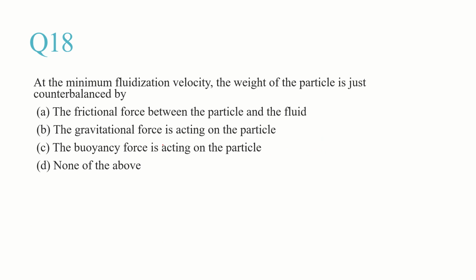This is a similar question. At minimum fluidization velocity, the weight of the particle is just counterbalanced by the frictional force between the particle and the fluid, gravitational force acting on the particle, buoyancy force acting on the particle, or none of the above. So at the minimum fluidization velocity, the weight of the particle is counterbalanced by the frictional force between the particle and the fluid.